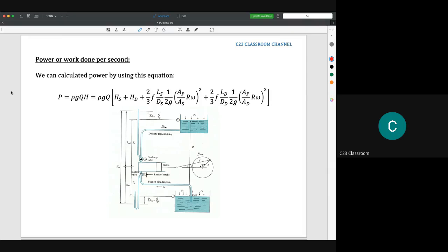Because power actually has a few meanings, it could include the frictional losses and so on and so forth. For a piston pump, please do not use the Bernoulli equation because the flow fluctuates. I think in the first notes for centrifugal and piston pumps, you know that the energy transferred in a piston pump is periodic, which means the water is not always full inside the pipe, so the Bernoulli equation cannot be used.